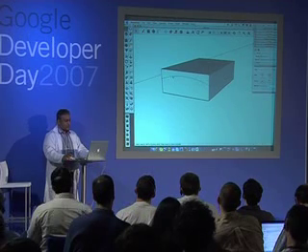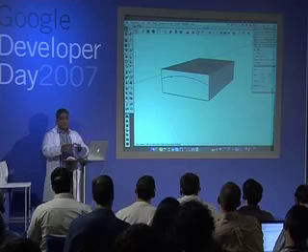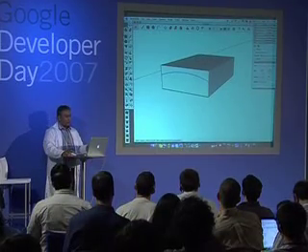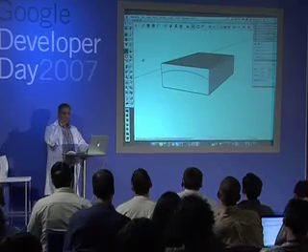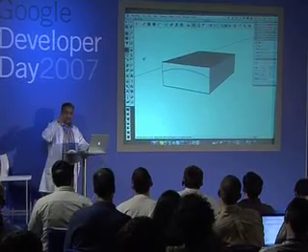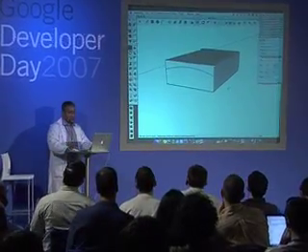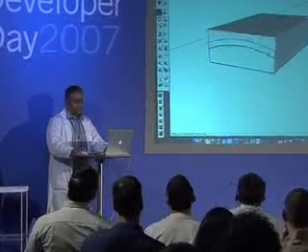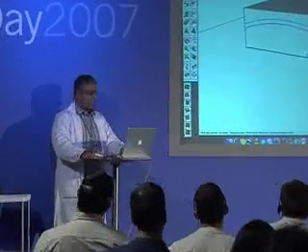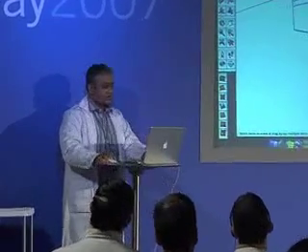I'll choose that line. To copy a line, to copy actually any element, all I do is use my move tool, but this time I hold down my control key. You see that little plus? That will move a copy at the same time. So here I'm going to move that copy vertically down. Okay. And now all I will do is erase the bits I don't need.